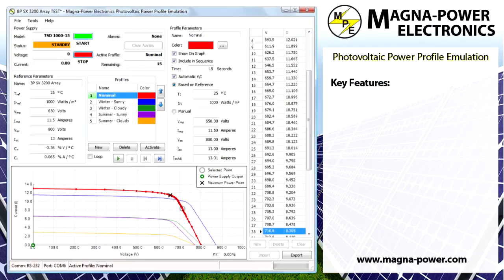A profile is defined to the power supply as 50 points along a curve. A greater density of points will be generated about the curve's nonlinear regions. The power supply will perform linear approximation between points. The resolution is much higher than the 50 points sent to the power supply.